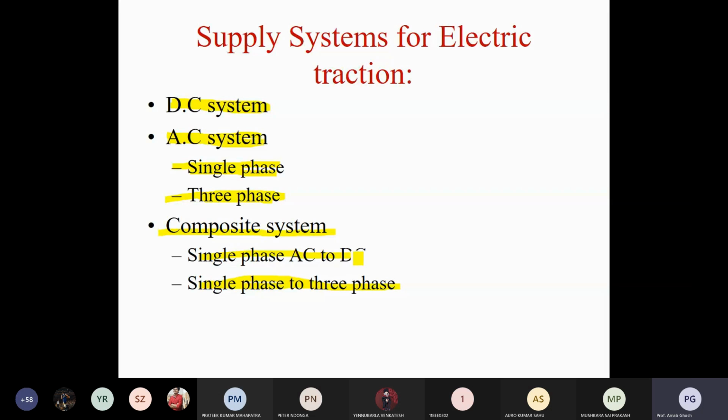If those connectors are off, the motor current will flow through the path with the additional resistance. So the motor current is less, meaning the flux value will be less, so you can go beyond the rated speed. Then to come back to the rated speed, you have to connect the bypass switch of that additional resistance. Just turn on the bypass switch, meaning it is short circuited, bypassing that additional resistance. So it will come to the base speed. That's the concept basically.